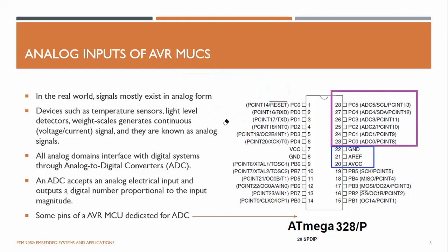In most of my projects, I also use resistor dividers when I need to measure something like a voltage level varying from 12 to 0. The microcontroller accepts voltage levels from 5 to 0. So you can simply use a resistor divider and map it to the level which varies from 0 to 5. Otherwise, it could harm the microcontroller. The calculation of the resistors is up to you. You can calculate them and map the voltage to the desired level of the microcontroller.